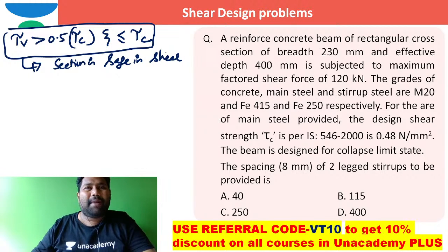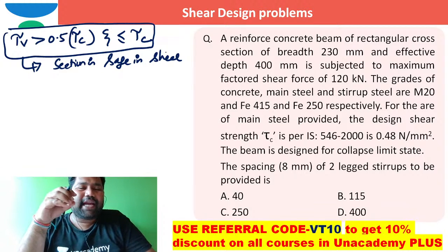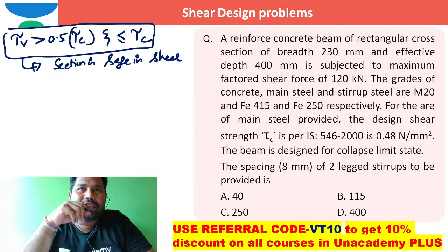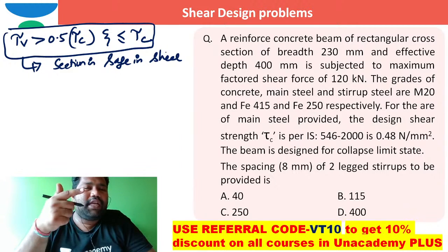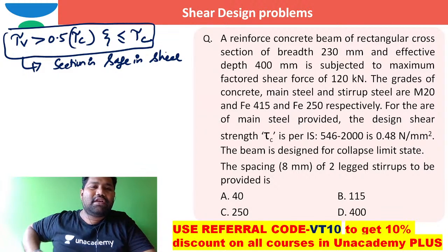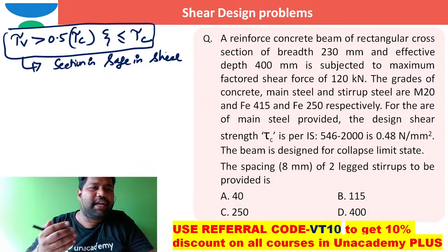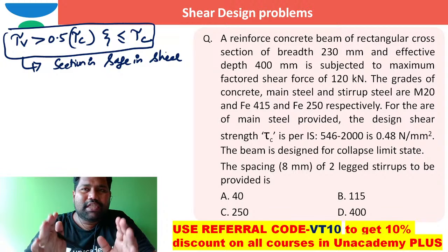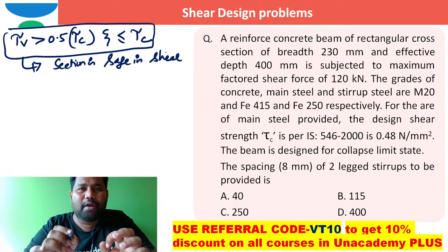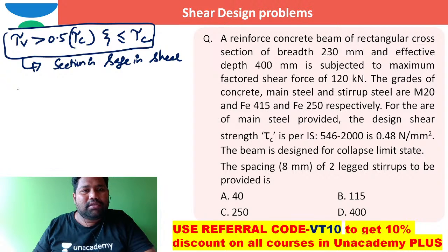There is no doubt. But in major designs, we generally don't consider the secondary effects, the stresses that come into the picture because of temperature, shrinkage, and creep. We don't generally consider them in calculations. To take care of those secondary effects, the code says that even when tau v is greater than 0.5 times tau c and less than tau c, and the section is still safe in shear, it will not fail in shear, but